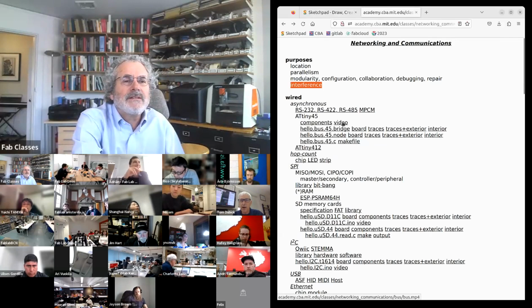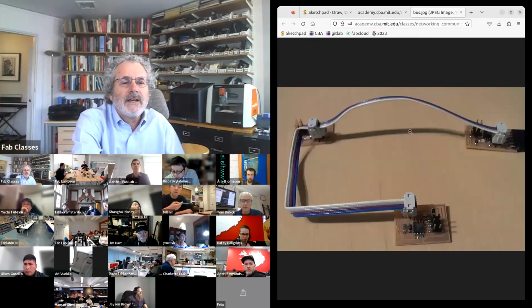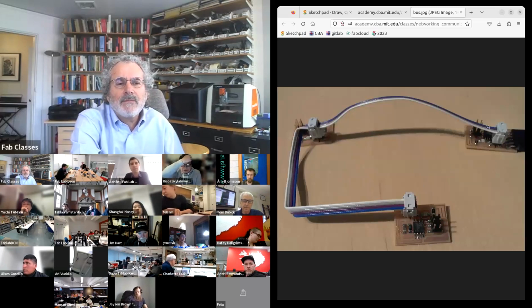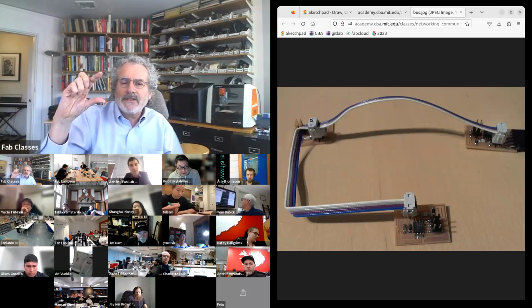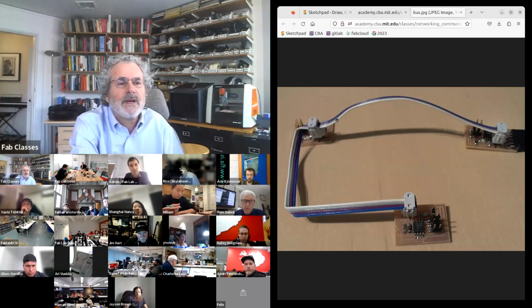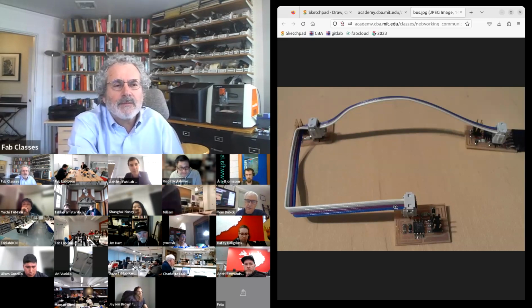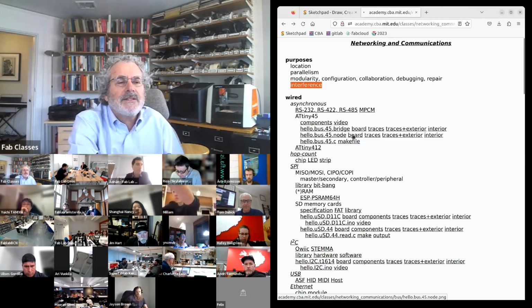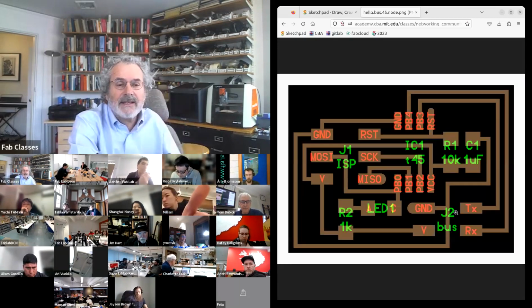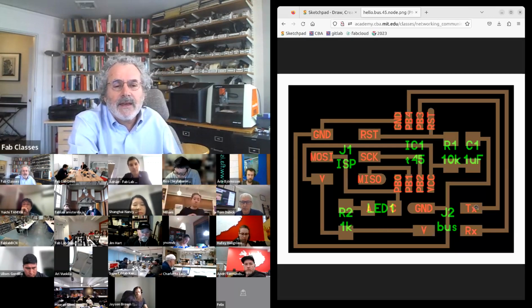And here's a really simple example of it. So in this simple example, I'm running a ribbon cable. These IDC, the insulation displacement connectors we use, the wire can go in one side and outside, so it can go to multiple nodes. Then on each node, I'm sending in power and ground, and then I'm busing transmit and receive signals.